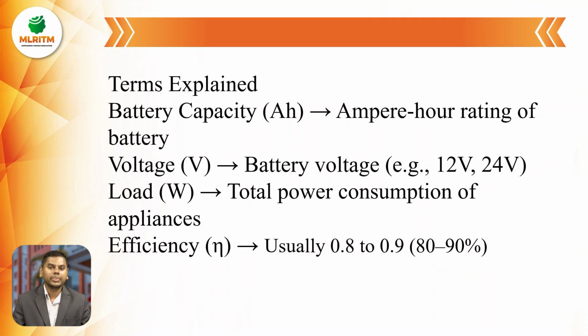Load is nothing but power. So here the load is the total power consumption of appliances. Next, efficiency. The battery efficiency is usually 0.8 to 0.9, so that is 80% to 90% only.